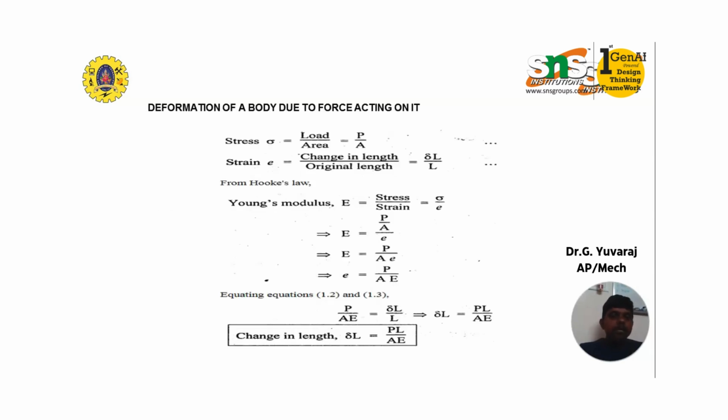When we study the deformation of the body, it is due to the force acting over the system. For example, to study the deformation of the body with respect to the force, we need to understand that stress is equal to load by area, and strain is equal to change in length by original length.